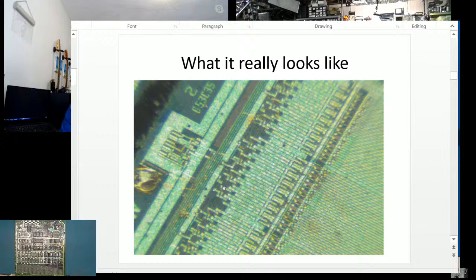Yeah. And then we had these little whiskers, and if the passivation layer was on there, they had to take the whisker and do what we called rape and pillage, to be honest. They would do this little back and forth and saw their way through the silicon nitride. Yeah. The passivation layer. Sometimes we had the chips made without silicon nitride on it. We could special order them that way. But then the chip would only be good for a week or two, is my memory. Not long. So it was a trade-off.